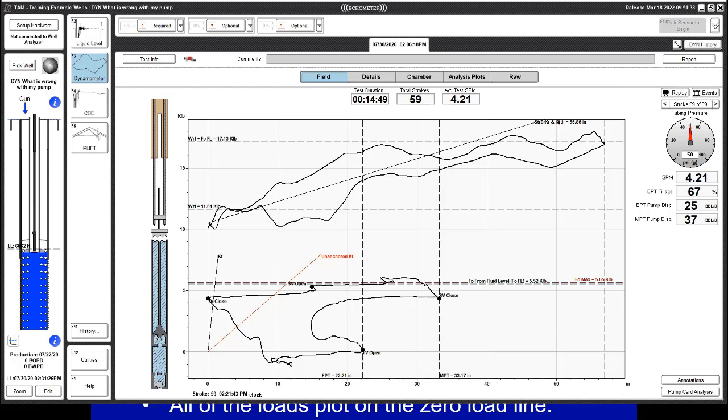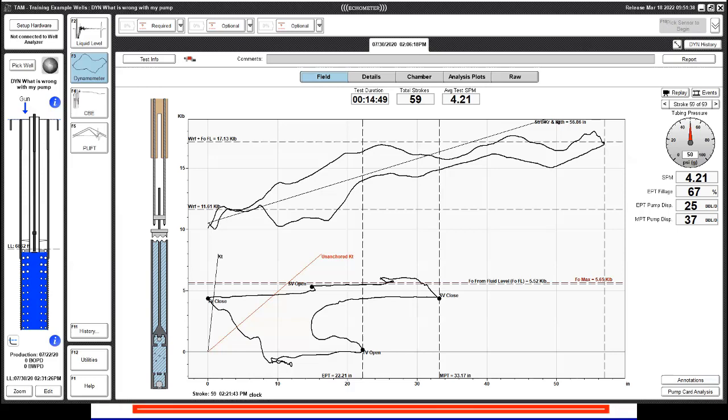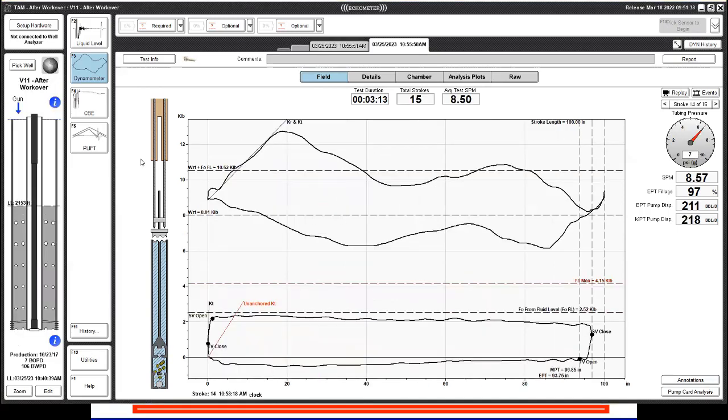While Gustavo's looking for that example, just to maximize our time and give him an opportunity to pull it up so he can further explain it, one of the questions I can answer is, can I use a polish rod transducer to conduct valve tests if the polish rod transducer doesn't measure real load? One of the things we emphasized was the difference between how the measurements were made between the horseshoe load cell transducer and the polish rod transducer. You can utilize the polish rod transducer to conduct valve tests. There is not an issue with that whatsoever.